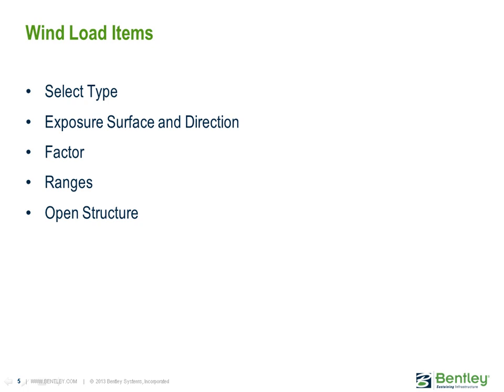Now, by default, STAAD.Pro assumes that structures are enclosed, and it seeks out closed loops formed by framing members, and then generates panels or closed surfaces based on the members in the range specified and their end joints. The area within the closed surface is determined, and the proportion of this area for each node in the list is calculated.